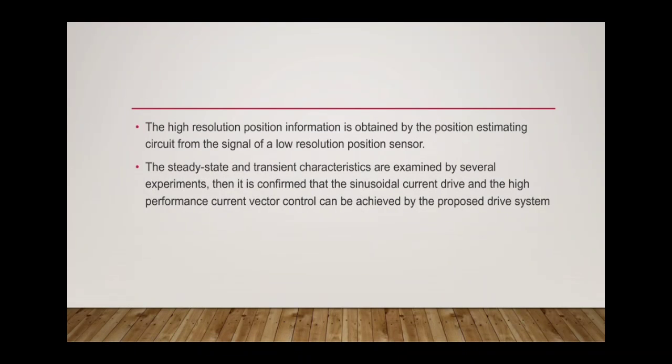The high resolution position information is obtained by the position estimating circuit from the signal of a low resolution position sensor. The steady state and the transient characteristics of the sinusoidal waves are examined by several experiments. Then it is confirmed that the sinusoidal current drive and the high performance current vector control can be achieved by the proposed drive system.